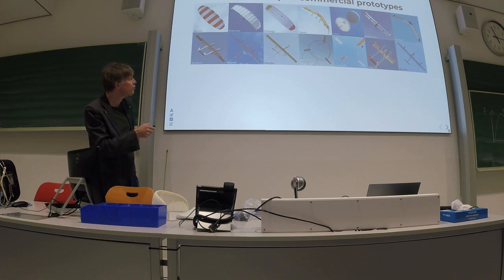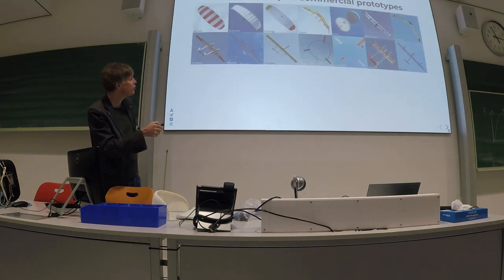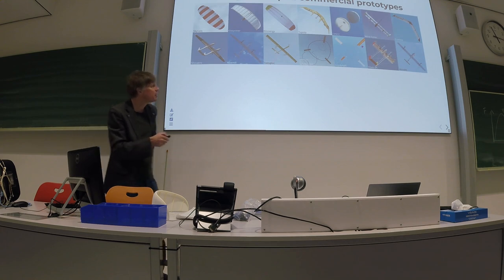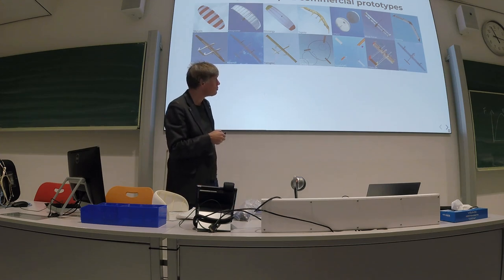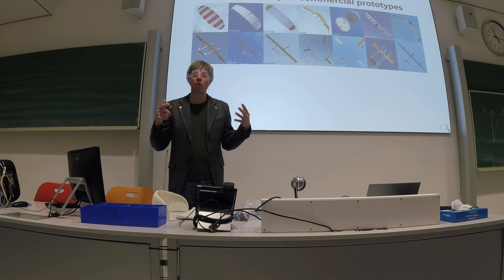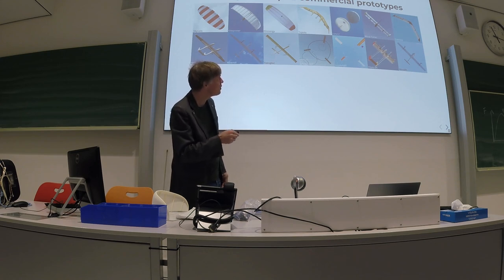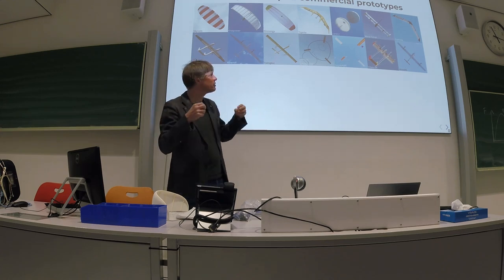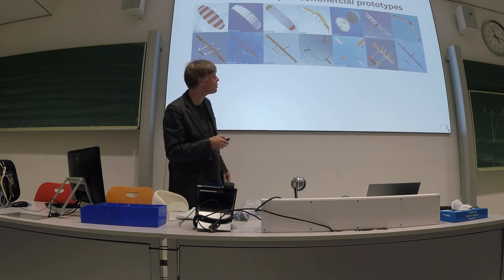So here you see the soft wing concepts, until here. So these first 4 typical soft wing kites. Then we have CPECC, which is Chinese, in operation since 2010 already. They use large parachutes to pull the tether off a drum with a pilot balloon or pilot parachute here. So this is a bit of a special concept. Then wind fisher, Magnus cylinder. So this is a rotating cylinder that creates lift. I mentioned this in one of the earlier lectures.